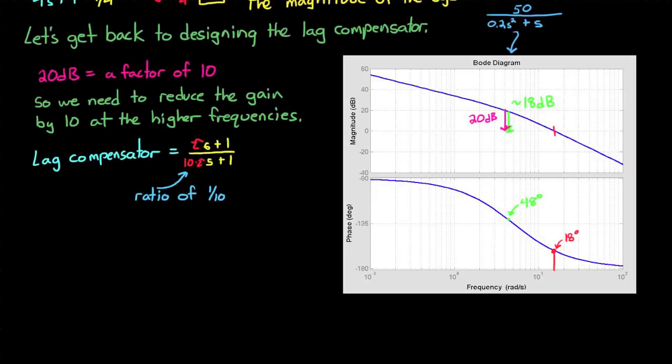Well, remember that we want our negative phase lag to be as far left as possible, which means placing the zero and pole as close to the imaginary axis as you can, or making the number tau as large as you possibly can. The larger you can make this number, the less the lag compensator will interfere with your original system. Remember, this is the same philosophy we used when placing the pole and zero when describing how we designed a lag compensator with root locus, always as close to the origin as possible.